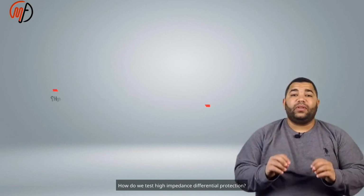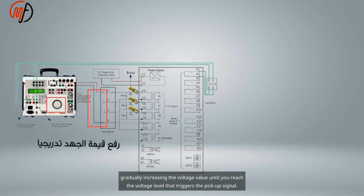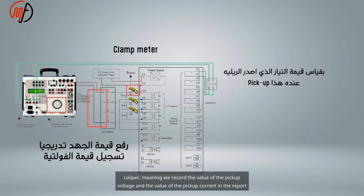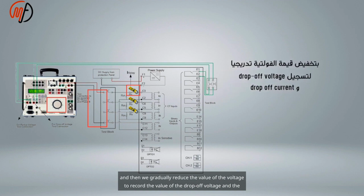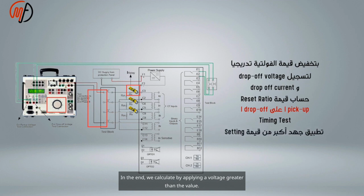The correct way to test this type of protection is by applying voltage, not injecting current, and then gradually increasing the voltage value until you reach the voltage level that triggers the pickup signal. At the same time, we measure the value of the current that the relay has issued at this pickup using a clamp meter, meaning we record the value of the pickup voltage and the value of the pickup current in the report, and then we gradually reduce the voltage to record the drop-off voltage and the drop-off current, and then calculate the reset ratio, which is equal to I drop-off over I pickup. In the end, we apply a voltage greater than the setting value.